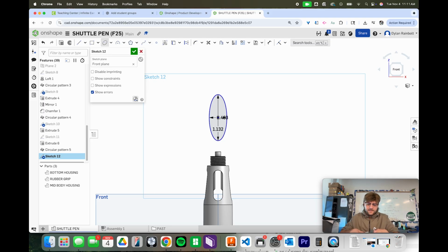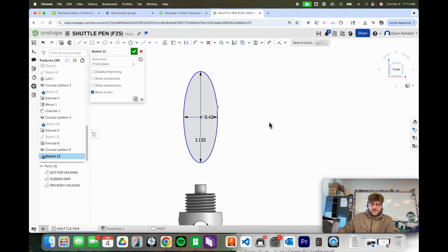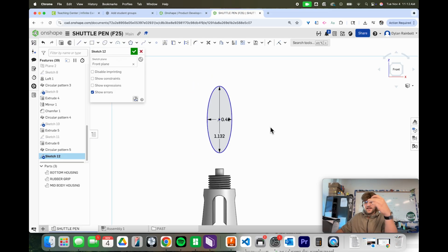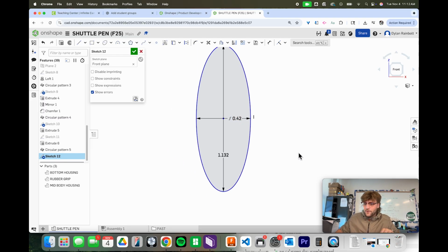What I could also end up doing is find this thickness here. And so the thickness of this guy is 0.14. What I can also do is then end up getting this. This thickness is 0.7. Let's do some quick maths here. So we got 0.7 minus 0.14 times 2. So we just mathematically determined what this inner negative space is going to be for the carabiner clip. So we'll end up going with that where it's 0.42 instead.